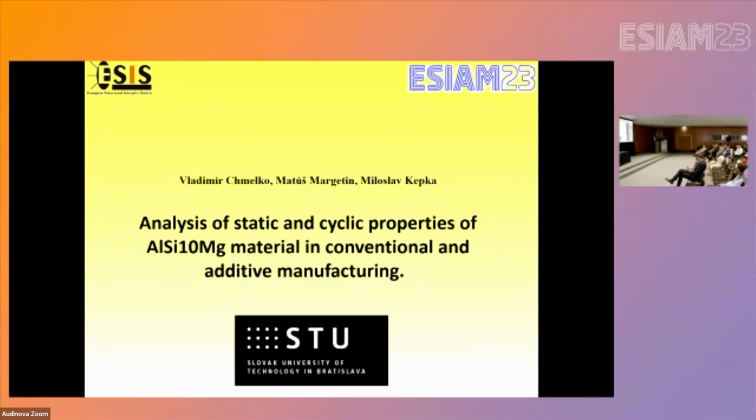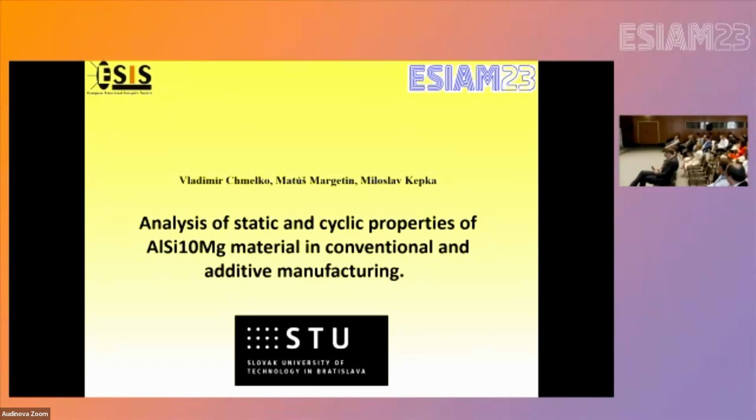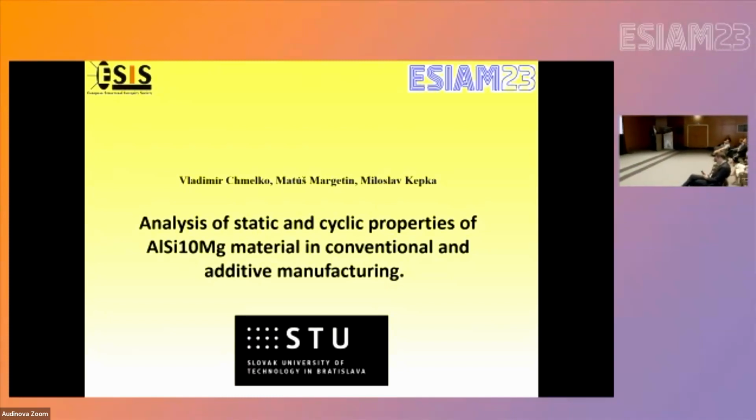Hello. Regarding conventional casting, are you talking about high pressure die casting? No, not high pressure. Conventional casting. Okay, gravity casting. Yes, so low pressure casting is possible to say. Okay, thank you. This is not from a bicycle frame, because for a bicycle frame it's necessary to use high pressure casting. Yeah, this is a conventional big piece from which we turn this specimen. Okay, because otherwise you also have a lot of defects in high pressure. Yes, but with conventional casting, if it's a big body, it is not so big a problem with defects. Okay, thank you.